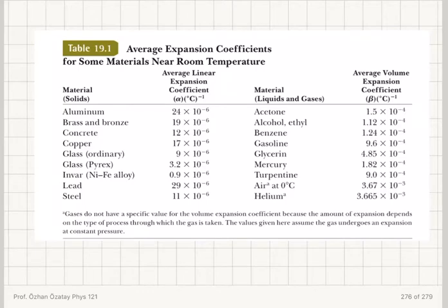Now, I can open this up, so I will find that V initial plus delta V is equal to L plus delta L, which is alpha L delta T, then W plus alpha W delta T, and H plus alpha H delta T. So assuming that I have the same linear coefficient of expansion in all three directions, this I can put in L W H parentheses.